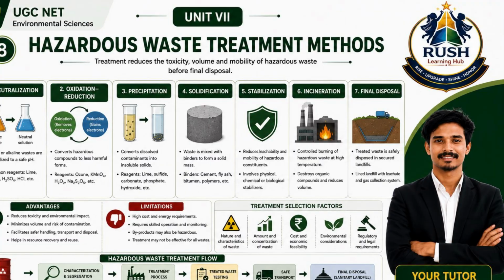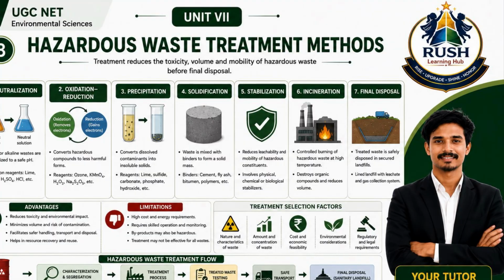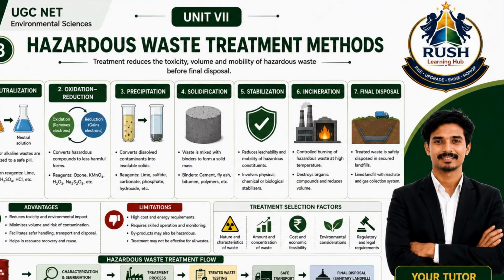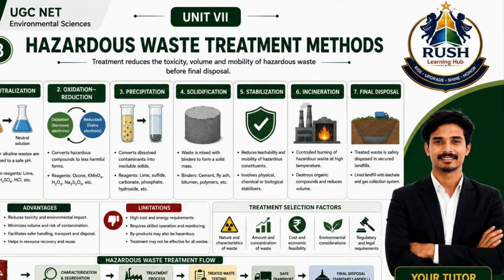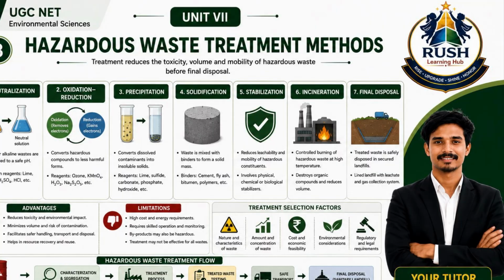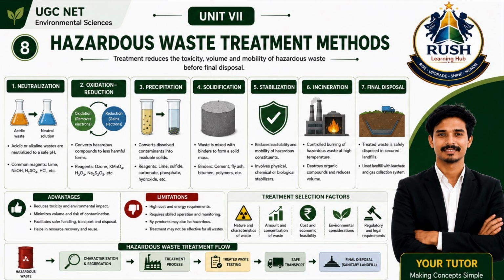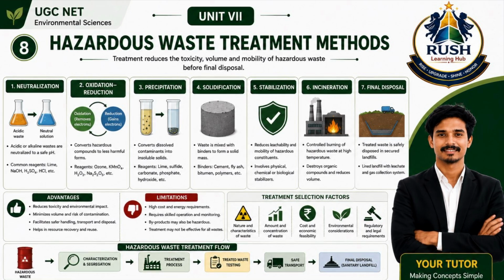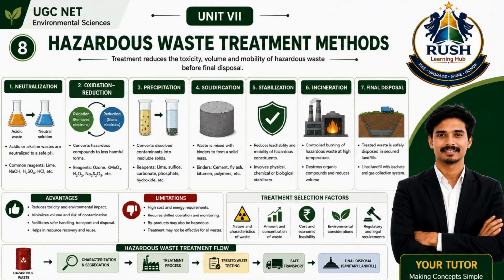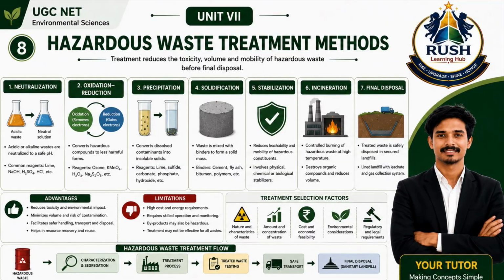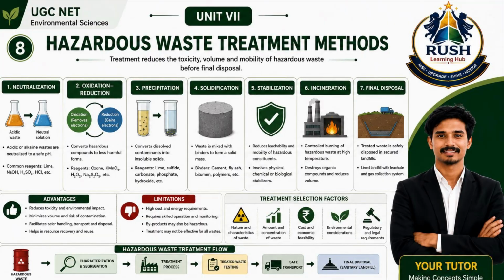Finally, let us discuss secure landfill disposal. After hazardous waste has been treated, some residues still require final disposal. These residues are placed in specially designed secure landfills. Secure landfills are different from ordinary sanitary landfills. They have multiple protective liners, leachate collection systems, groundwater monitoring wells, landfill gas management systems, and long-term environmental monitoring. Their primary objective is to isolate hazardous waste from the surrounding environment and prevent contamination of soil and groundwater.